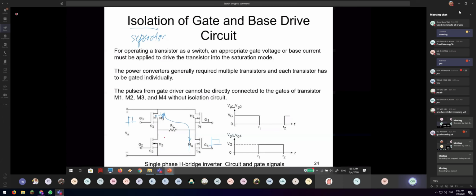So this is also all N-type now. Sometimes it can be one pair of N-type and one pair of P-type. It depends. Here is the same. If this one is high, here is high, and then this will be turned on, so the current will flow this way. So you can see this is how you can control the direction of polarity of your motor device or other device.